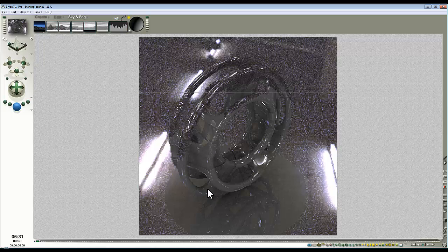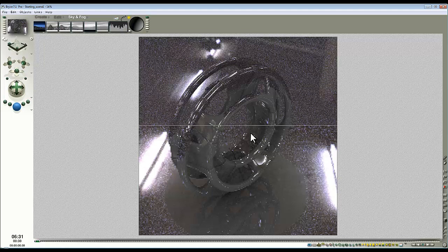And what you might also notice is that there's not quite enough light to light this object in the scene. So what I want to do is produce a hypertexture that's going to boost my output for the ambient on the surface of the light source, so I can produce enough light to light this properly. And then after I've done that, I shall look at taking the effect a bit further, because you can utilize that to increase the contrast in the transient render mode, so you can exaggerate the effect. You can see it's looking okay at the moment. I'll just stop the render there and then modify this material.